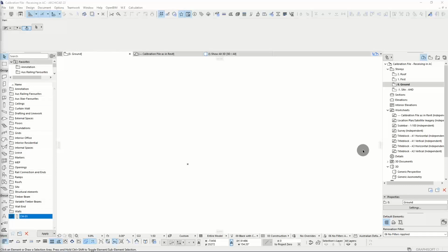In that case, we need to make sure that the translation that happens inside Archicad will build IFC geometry in a way that can be reconstructed by the receiving software with the native tools, because that's going to be the only way you can then carry on a design. Otherwise, you're going to have to rebuild things, and you want to minimize the amount of those items.